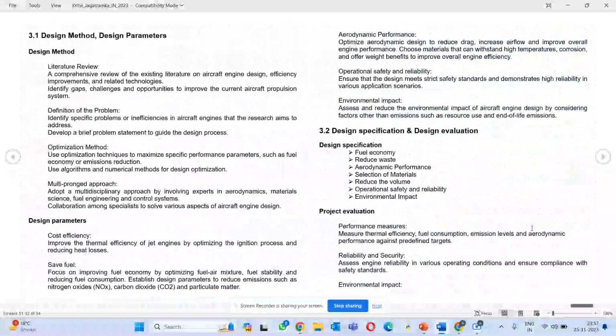To conclude, I would say that it's clear that these are marvelous machines. The key takeaways include the importance of the fan in the air propulsion, the role of the compressors in preparing the air for combustion, and the significance of the turbines in extracting energy from the hot gases produced during the combustion. The nozzle, as the final stage, plays a crucial role in converting the high velocity exhaust gases into forward thrust.